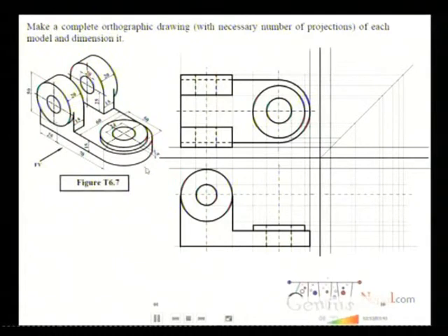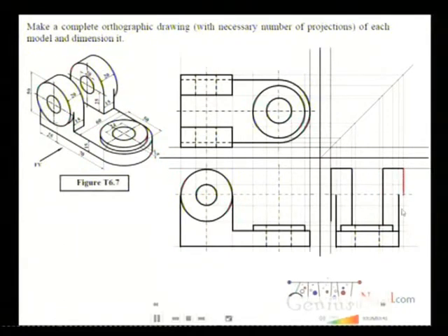If we look from the right side, these are the points, a grid of points, and after drawing this grid of points, let me pick up points one by one. The width is 60, so at a distance of 60 draw a horizontal line. This thickness is 15, so at 15, and again 5 mm thickness for this portion. Diameter is 60. These lines show these edges, 20 mm width, upper and lower. This one 20. Vertical lines on both sides. Again here thickness is known to us, that is 5 mm on this side, 5 on this side.